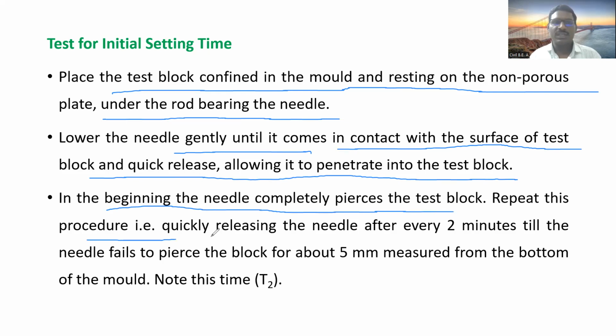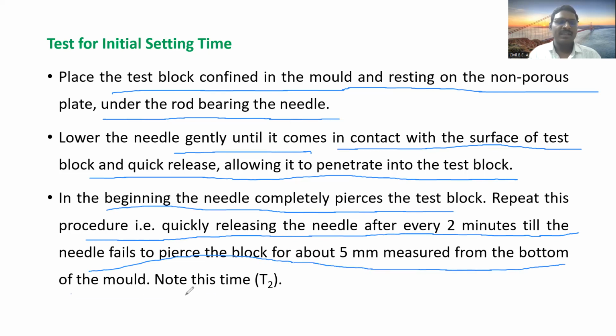Repeat the procedure, quickly releasing the needle every 2 minutes, till the needle fails to penetrate beyond about 5 mm measured from the bottom. We have to insert the needle until the 5 mm distance is measured from the bottom. And that time we have to record as T2.